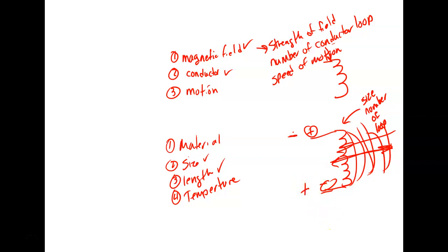So this counter EMF, and in one of the other classes, let me demonstrate this to you. We have a neon light bulb that we put across a DC source, and it takes over 90 volts to make it glow. We take that neon light bulb and put it across this coil, and we charge this up to 12 volts.